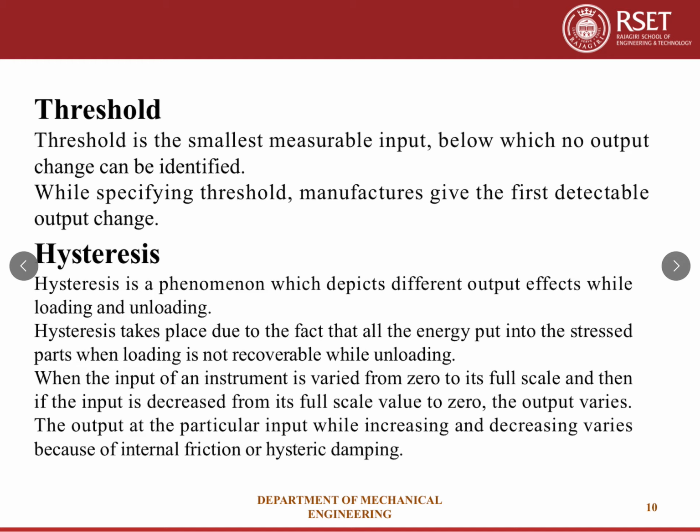We increase the loading from 0 to the maximum value; for a particular input, there is an output. When we reduce the load from the maximum value to 0, for the same particular load, the output value will be different. That is due to hysteresis. It is similar to magnetic hysteresis; there is hysteresis in mechanical instruments also.